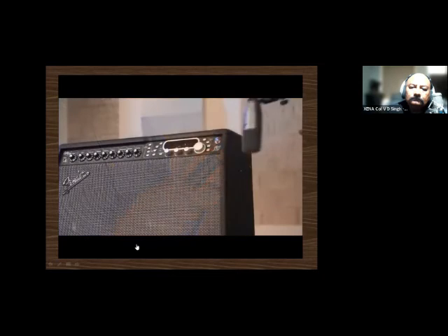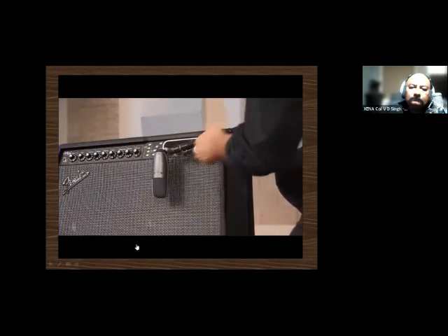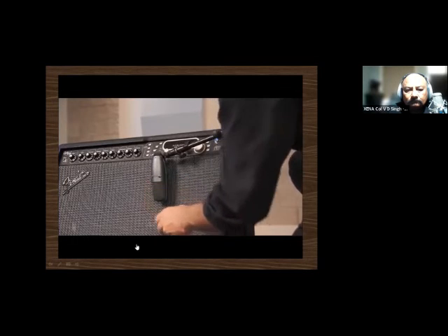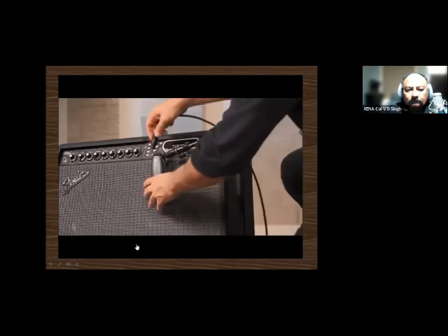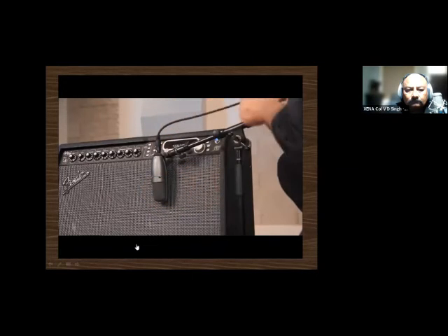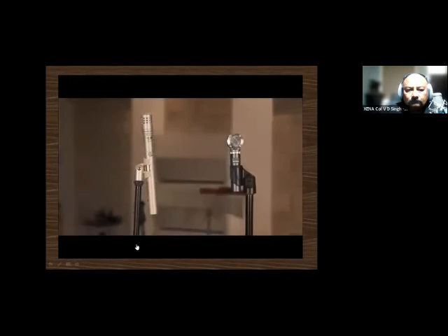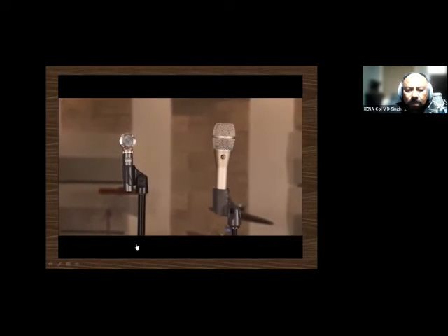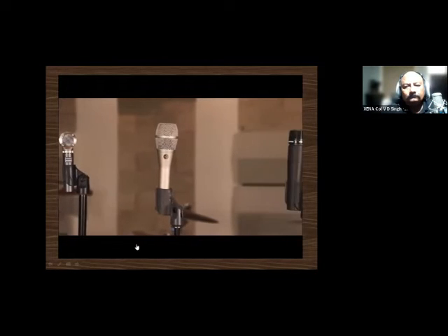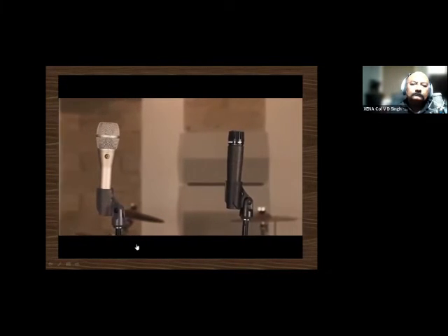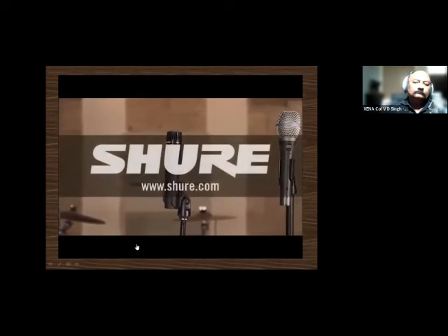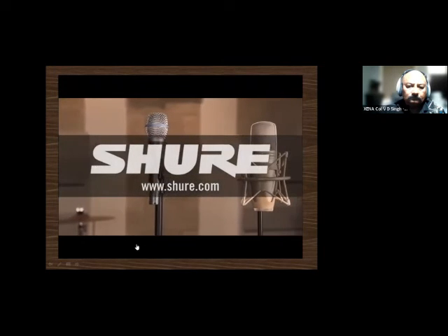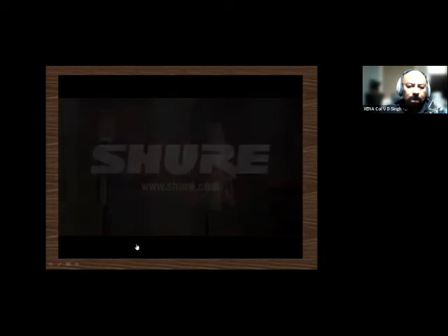Unlike dynamic mics, the electronics in a condenser mic can overload when exposed to very loud sounds. Make sure that the condenser mic you're using can handle the sound levels that the source can be expected to produce. By understanding microphone characteristics like operating principle, you'll be able to choose the best mic for any application and get better results when recording or using a sound system. In part 2 of this series, we'll explain microphone frequency response. To hear samples of how different microphones sound, visit the Shure Mic Listening Lab at shure.com.